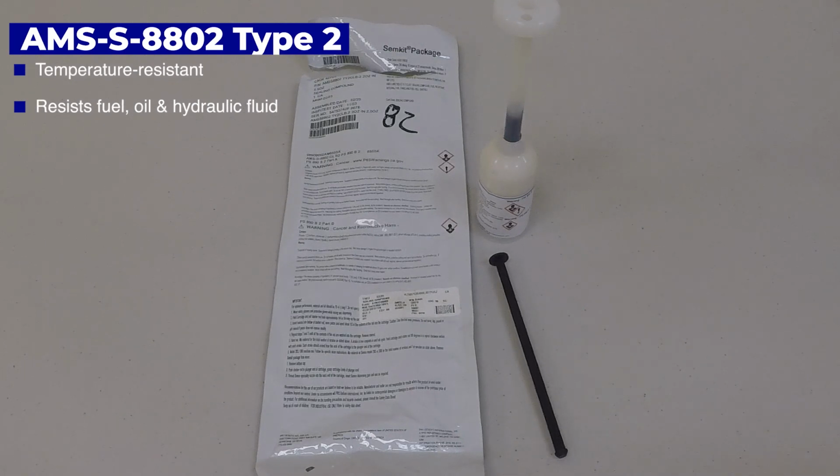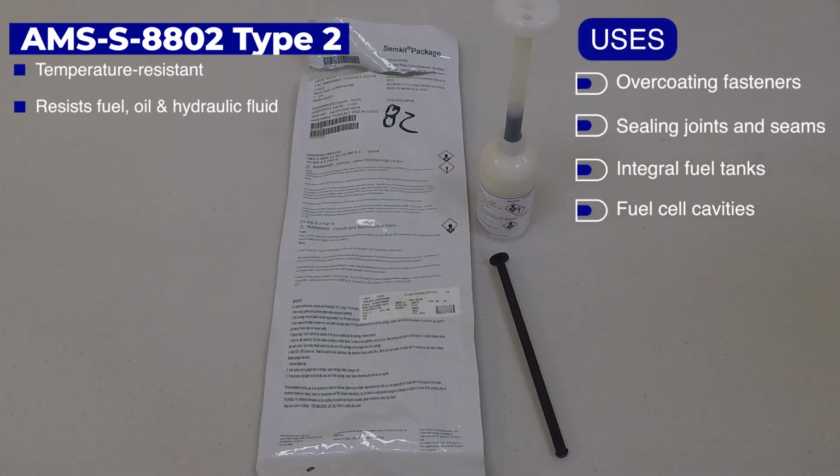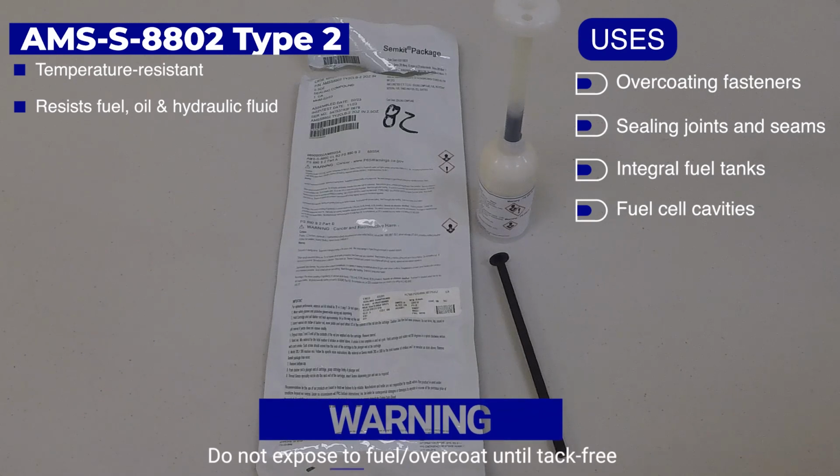AMS-SAE-AS-8802 Type 2 is a sealing compound that is temperature resistant and used on integral fuel tanks and fuel cell cavities. This sealant resists fuel, oil, and hydraulic fluid. Sealant used in overcoating fasteners, sealing joints and seams, integral fuel tanks and fuel cell cavities. AMS-SAE-AS-8802 Type 2 should not be exposed to fuel or overcoated until tack-free. No corrosion inhibitors.